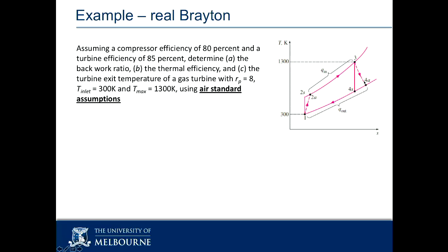When we think about it in terms of the work done, so Q minus W equals delta H, on the isentropic process, or in the ideal gas process, we drop the Q, we're saying they're adiabatic, maybe this breaks down, but we're looking at a delta H. The work required to run this guy is a CP delta T, which is to say, my delta T is here, and if I have losses and friction and whatever, my T2A is higher, is bigger, which means the amount of work required to run an inefficient compressor is more. It's harder to run an inefficient machine.